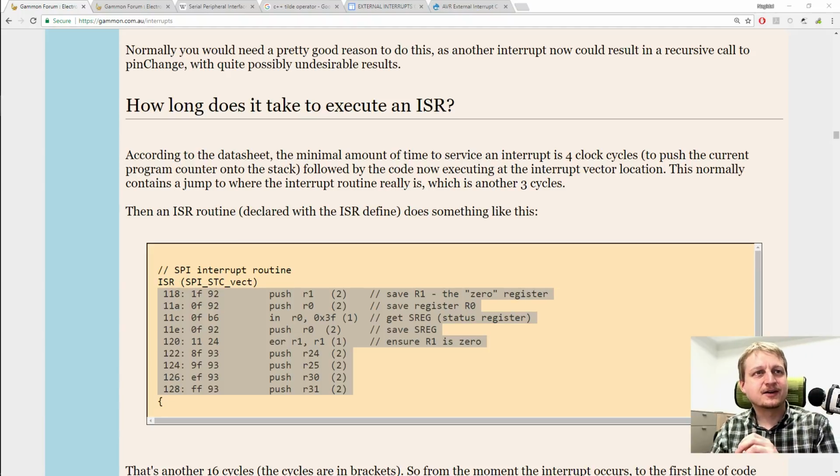Yes, Ferko, the RPM meter is related to the Arduino Tapper project because I need to figure out a suitable translation ratio of the DC motor. It rotates too fast. I can't have the axle moving the tappers rotate that fast as the motor rotates.